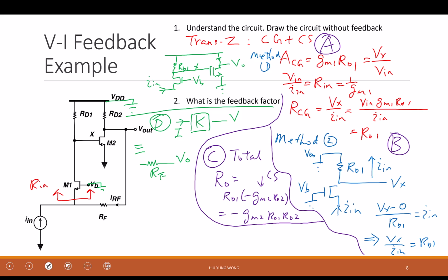Well, the current's... Someone say, there's no concern because it will just open, right? And then how about here? Then you also say source to the source of this transistor, right? So I do have an impedance going up. You can just draw the whole transistor if you want, M1 or everything, that is fine, up to you. But we don't want to do that. We just want to find the effective resistance. Okay, he said 1 over GM. Do you agree? Because looking up is 1 over GM1.